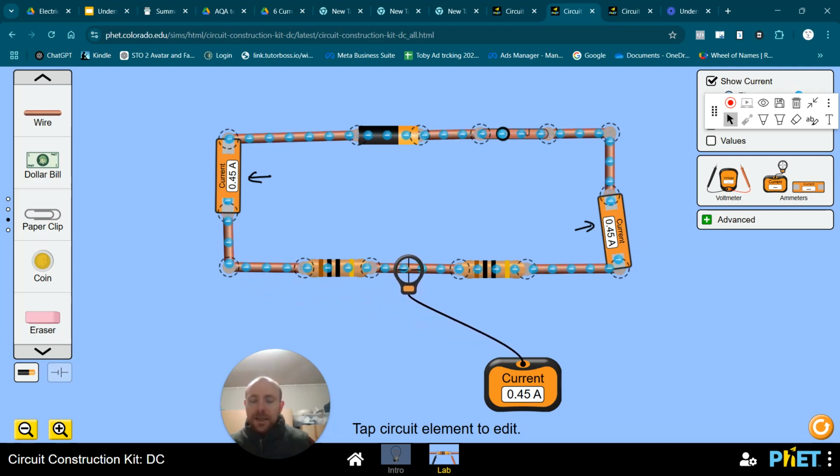I go through this resistor. No current has been used up in going through that resistor. It's a flow. Flow doesn't get used up. So it's still 0.45 amps all the way through. In a series circuit, that's exactly what will happen. Anywhere in that series circuit, the current is the same. Everyone does get that, but when you're doing questions, people sometimes forget that. Have that in your mind: the current in a series circuit is the same anywhere in that series circuit.